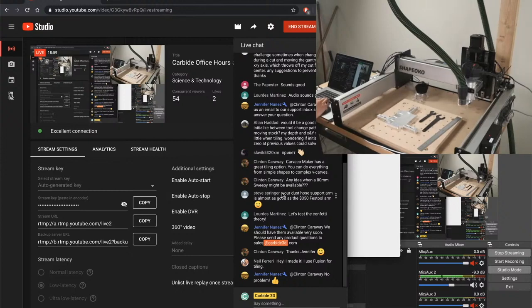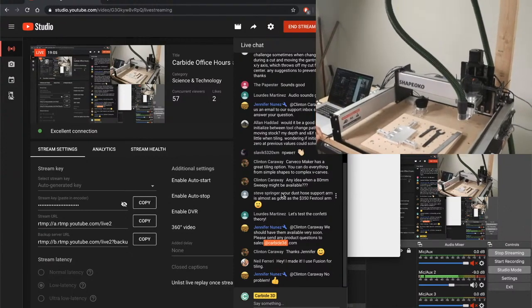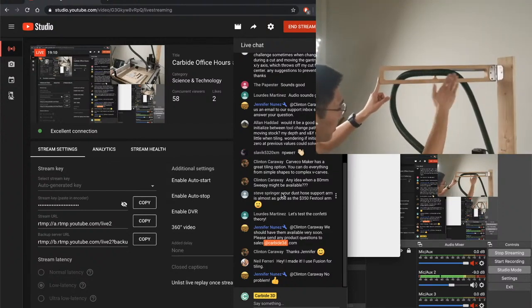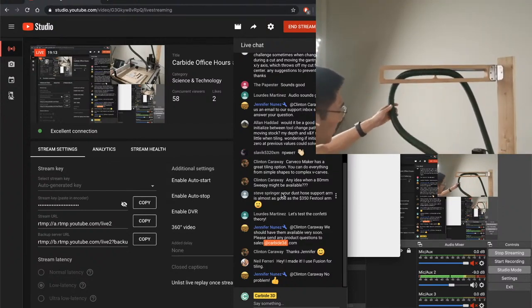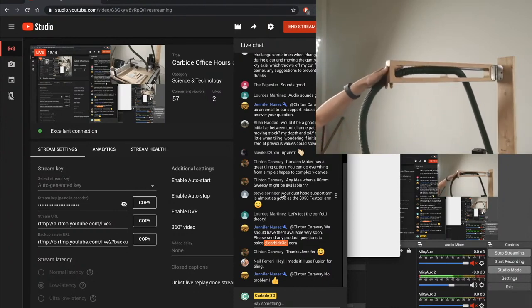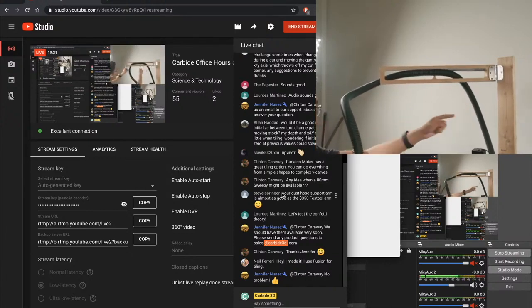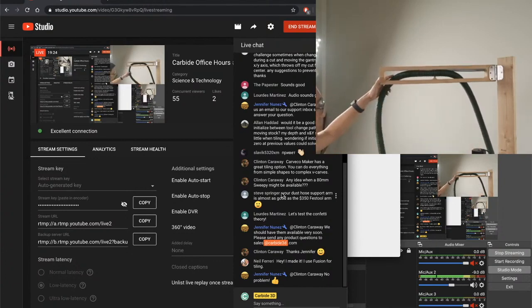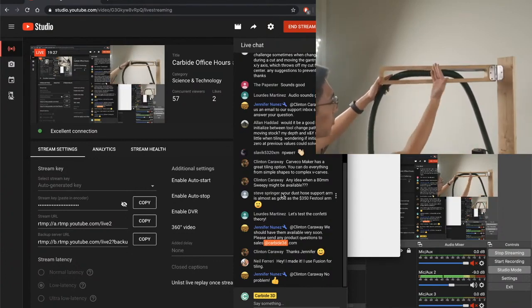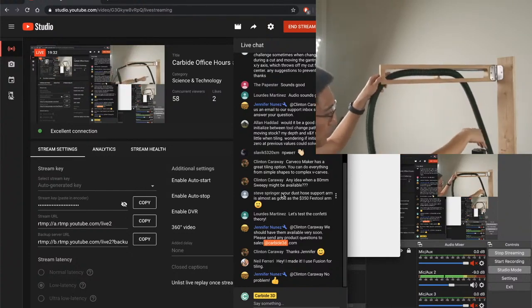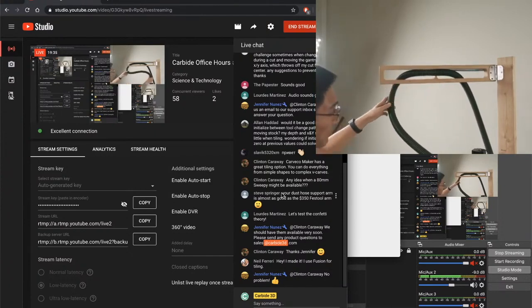Yeah, this Desto support arm, I've been really pleased with it. At home, I actually split this up into two linkages for a little extra articulation, because what you'll notice here is this can swing out, but for the hose to go all the way back to this back corner, the hose has to go all the way here, whereas if you have a two-link design, this can fold in on itself and bring this end of your arm back over to the back right corner of your machine. But really simple hardware solves a lot of problems.